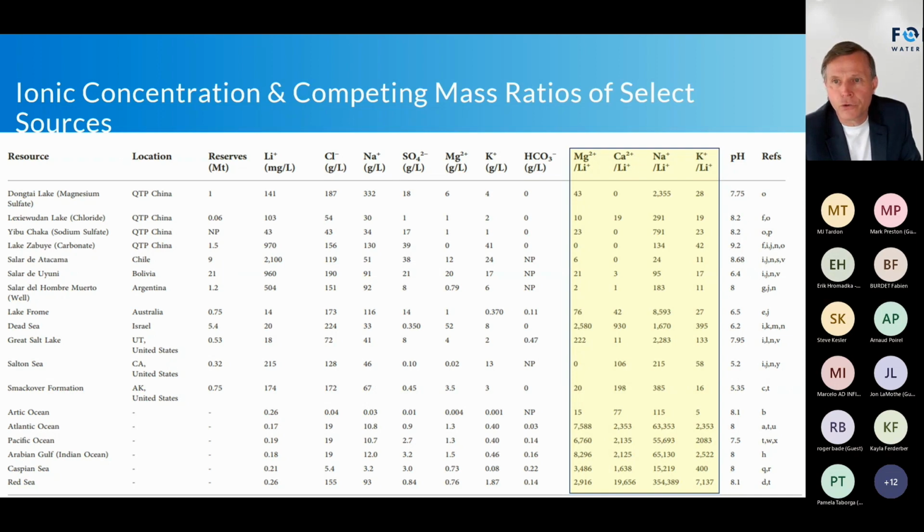Well, if I change the pH, that may enhance or impede the performance of the exchange for different materials. Temperature is another one. Some DLE processes operate at very high temperatures because that aids. So again, different materials and selections, but these are the ratios of the materials we want to take a look at.